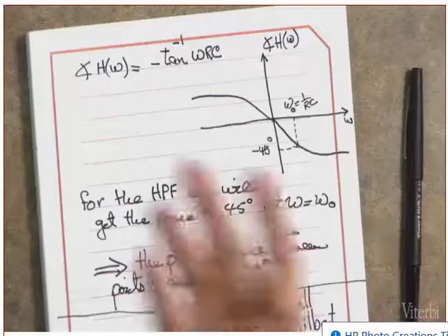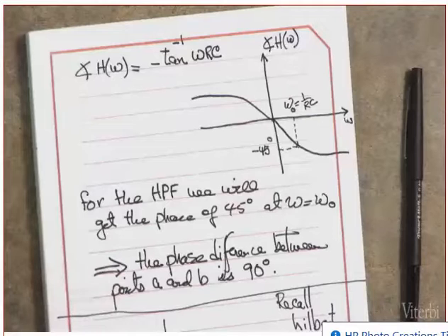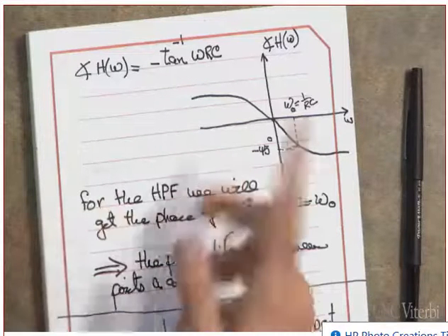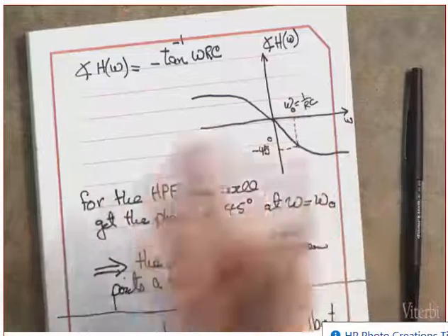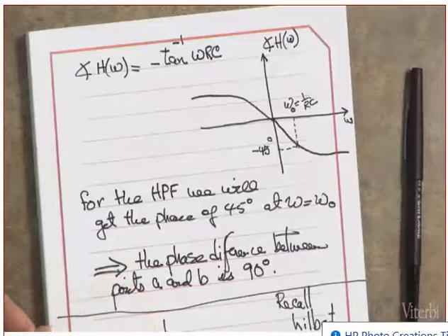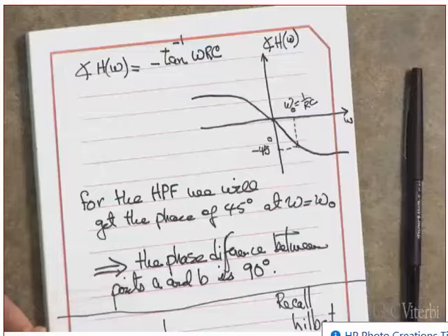I cannot hear you, my dear. We use R equal to 1, we use C equal to 1, and we get omega naught equal to 1. But we can choose R equal to 2, C equal to half, and still get the same omega naught. That's true. So the values of R and C will determine the design. The question is whether we should choose the RC value with the same omega naught, or choose R1 equal to R2 and C1 equal to C2, from the low pass filter to the high pass filter. The RC should be equal, or the time constants should be equal.